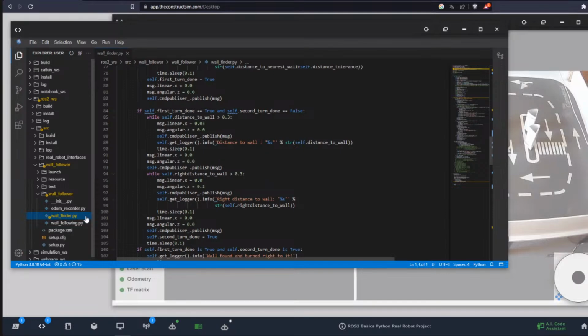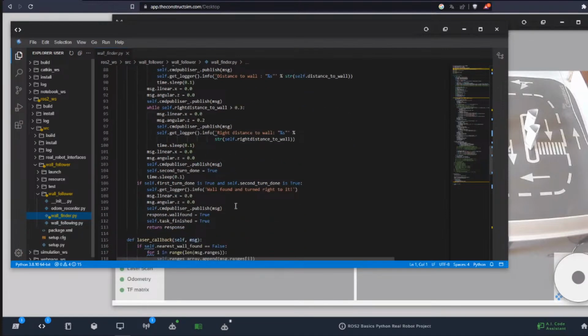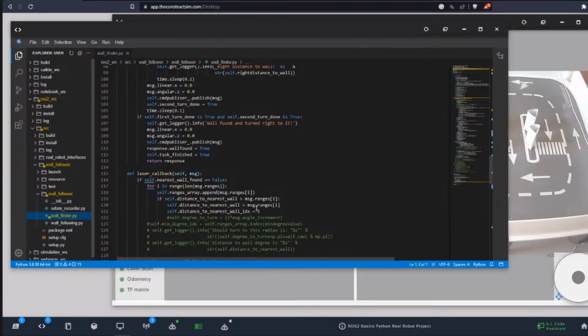And then you get rid of those extra callback groups that might be getting in the way for the rest. Yes, since I'm not going to use the wall finder again, the one thing I could do is add the feedback and get the laser callbacks from here and not shut down wall finder. That actually is a great idea because you're saying change the service server to an action server and get feedback. Is that what you're saying? Yes.